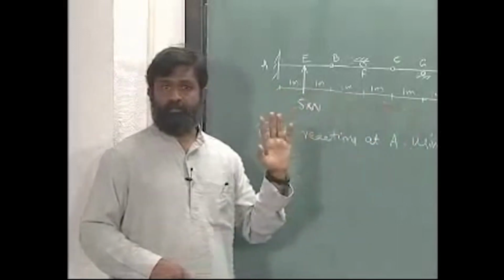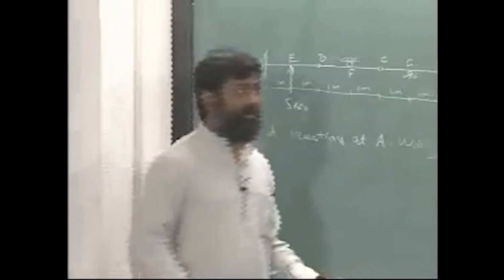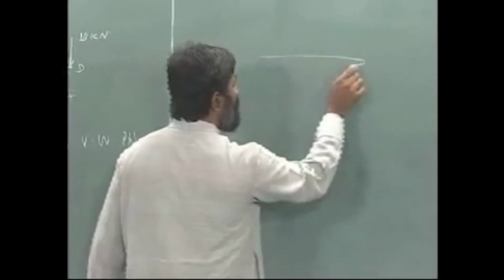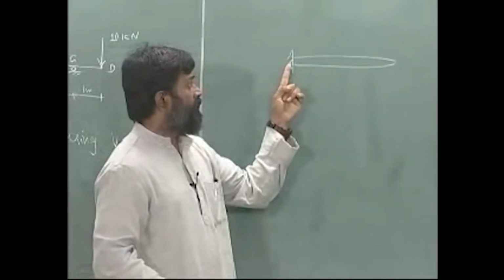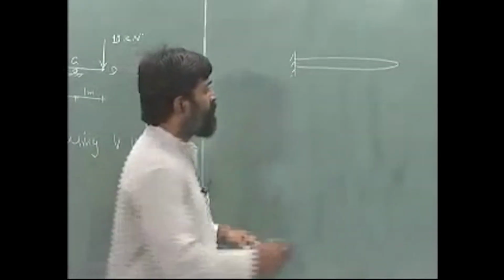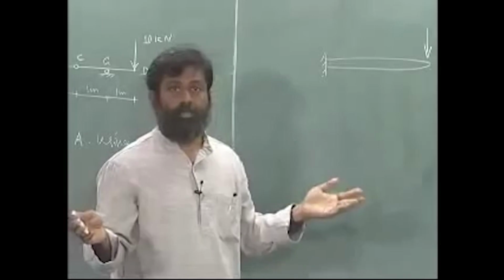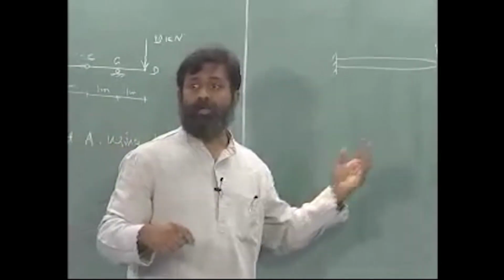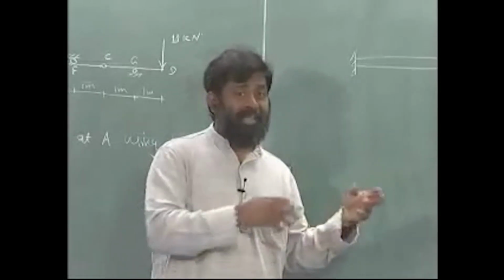To find the degrees of freedom for a beam we already know. Let us just have a recap. If I have a beam like this, at this point it is prevented from rotation as well as movement. Okay, it is a beam problem, which means horizontal displacement is redundant. Okay. So if I apply a force here, is it going to be stable? That is the question I am asking. Okay, if it is stable, what is the degree of freedom I have? Is it positive, 0, or negative?